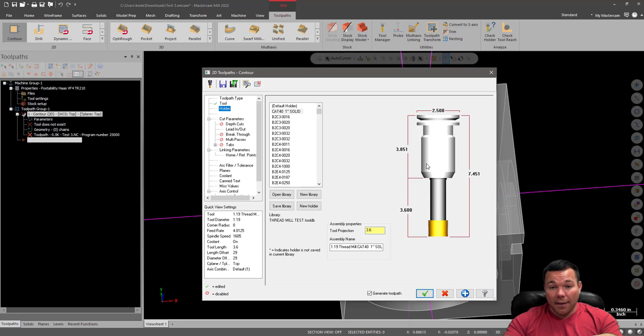Now that being said, a simulation that runs correct is no substitute for putting it on 5%, turning everything down the first time you run it, and making sure you have your finger on the feed hold button. I'm always extremely careful the first time I run it, no matter what. I don't care what the simulation shows, but the simulation is right 99% of the time.